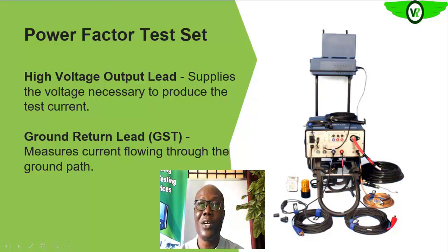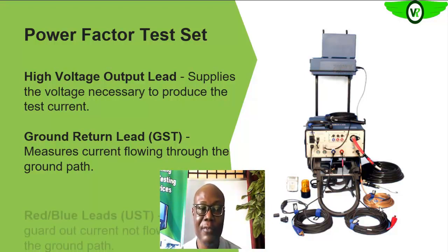That ground lead is basically for grounding the equipment, connecting it to the ground of the equipment that you want to test. And remember, the equipment will also have its own ground, so that ground will be secured, and the ground lead connected to that particular ground. Then we have the